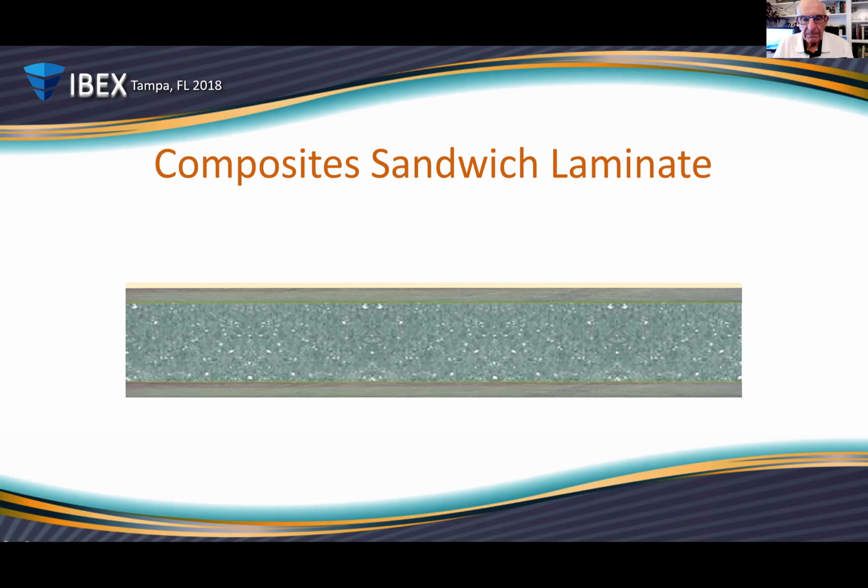So we have, in this case, two fiberglass skins encapsulating a core material. That core could be any type of core that you'd be inclined to use, whether it's PVC foam or balsa or some type of honeycomb. And then we have gel coat on the surface.